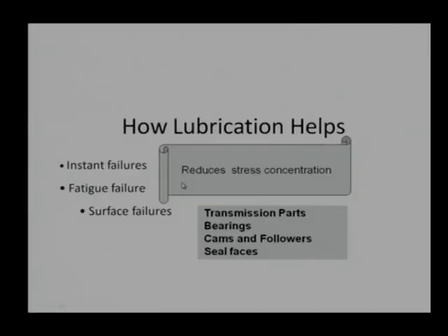And this stress concentration factor, which has been emphasized, is common in a number of devices like transmission parts. If we do proper lubrication, the stress concentration in transmission parts will reduce. Similarly in bearings, where some micro pits are generated or the surface is slightly irregular, stress concentration can be reduced. Similarly in the cam follower mechanism, which has rotational as well as reciprocating motion, the stress concentration factor will reduce.